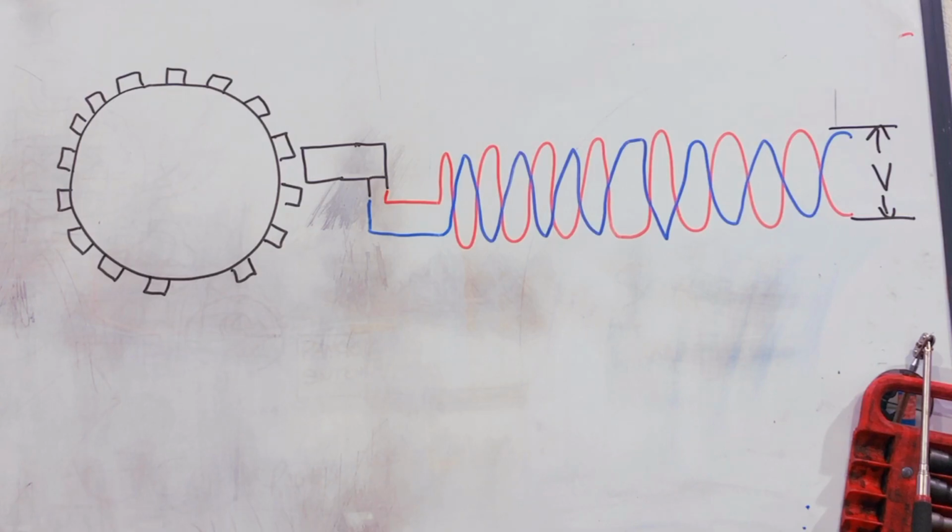So here we are at the not so whiteboard again with one of my famously crap drones, just to basically give you an idea of how the crankshaft sensor works on this vehicle. The crank sensor on this vehicle is an inductive type sensor, which means that it actually creates its own voltage.